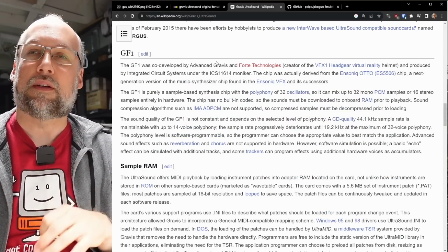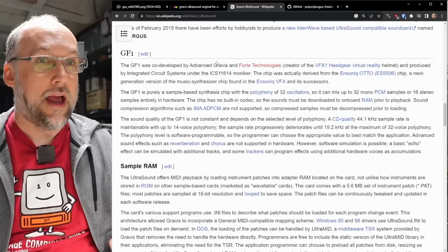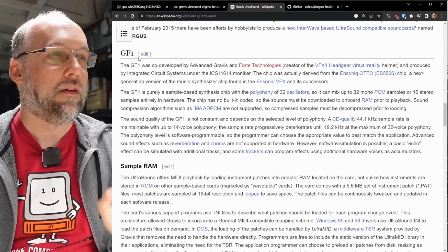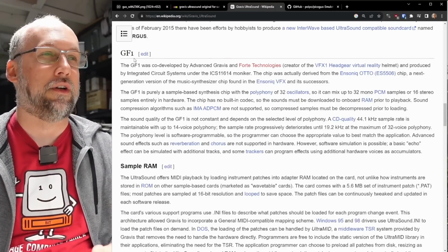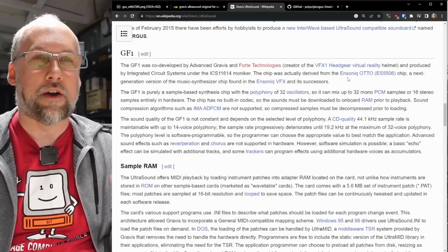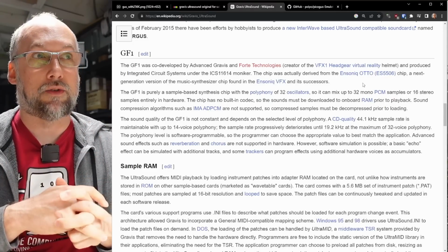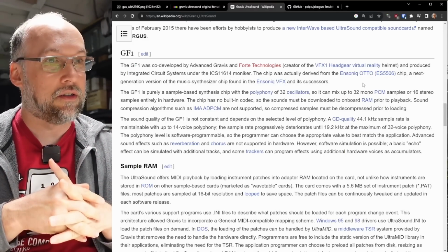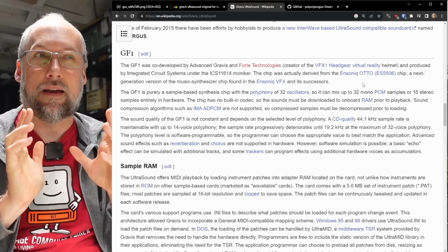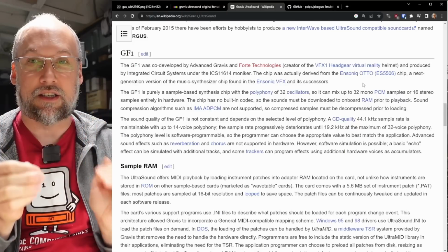This type of hardware mixing was really the domain of expensive sampling synthesizers and then computers like the Commodore Amiga and the Apple II GS. In fact, the GF1 architecture here that's on the Gravis Ultrasound was based on the Ensoniq Ottochip, and it was actually an Ensoniq sound chip that powered the Apple II GS with, I think, 16 channels of hardware mixing. The thing about the Apple II GS, though, is it only had 64K of sample memory, so all your samples had to fit in that 64K.